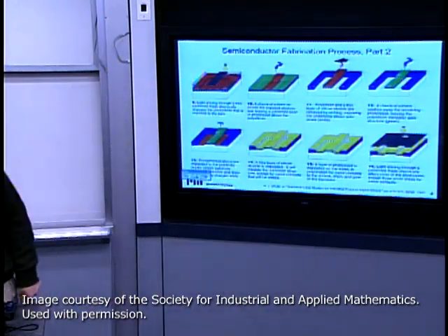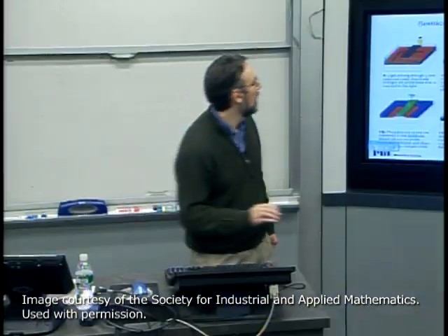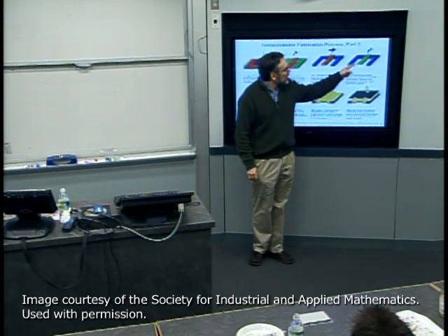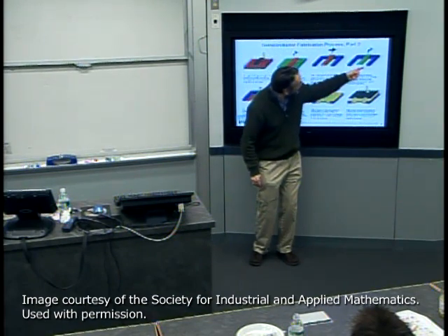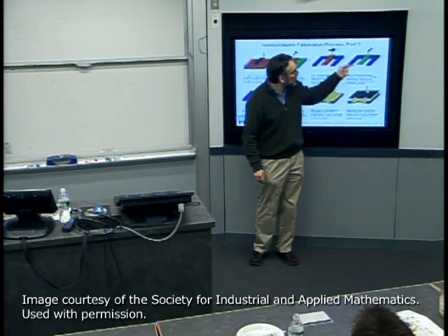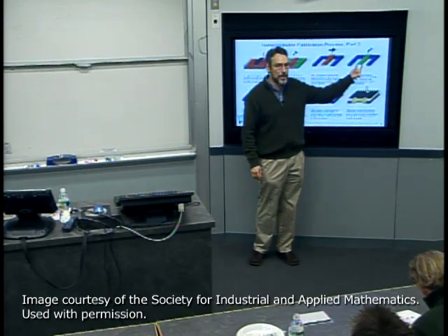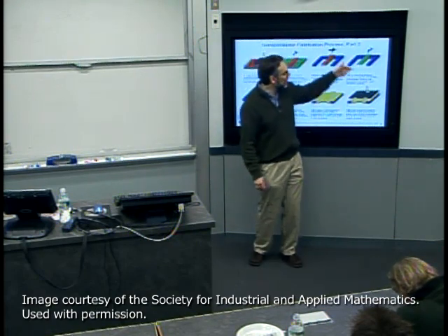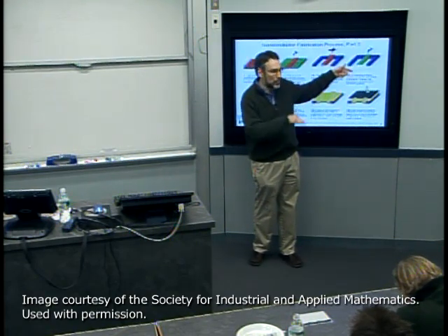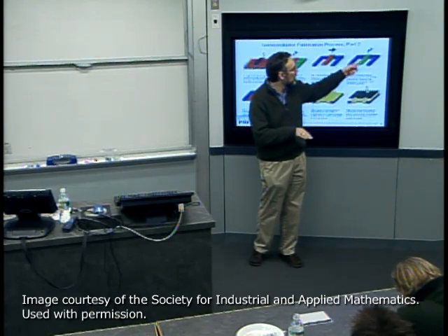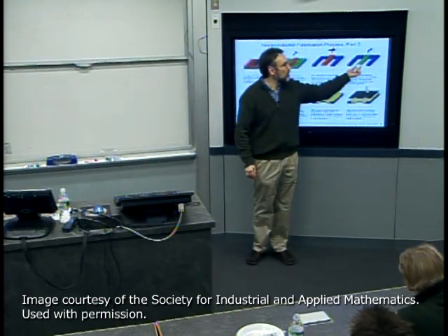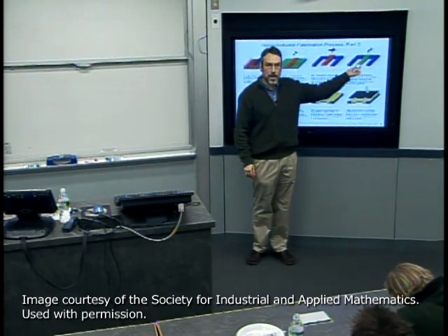Now, this structure right here is very, very critical. This is the gate electrode. Again, the current is going to flow in this direction along this length underneath that gate electrode in the silicon. And this is referred to as the channel length. So the channel is the structure that we're going to create underneath the silicon. And the length of that physical electrode is very, very, very critical in determining many of the most important characteristics